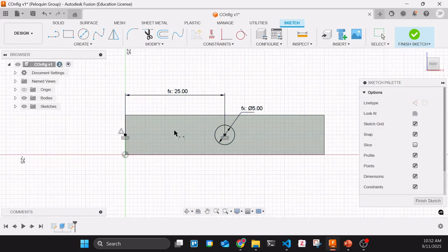And so what just happened is we have a 50 millimeter length plate. We have one hole. And so our equation here becomes number of holes is 1, 1 plus 1 is 2. The length divided by 2 then puts this hole exactly in the center between the two edges of the plate.